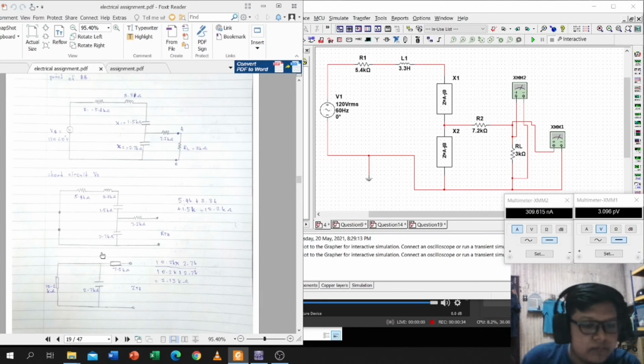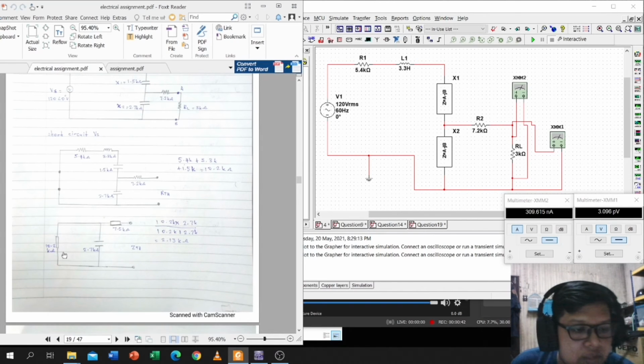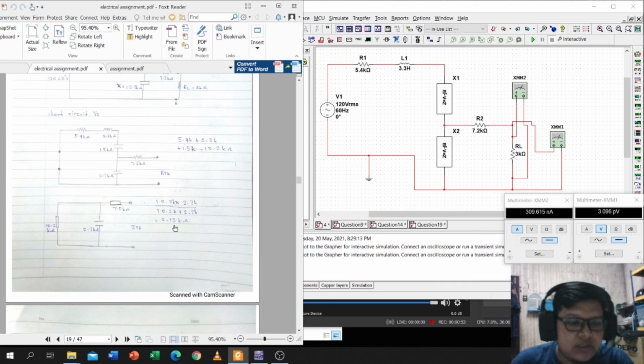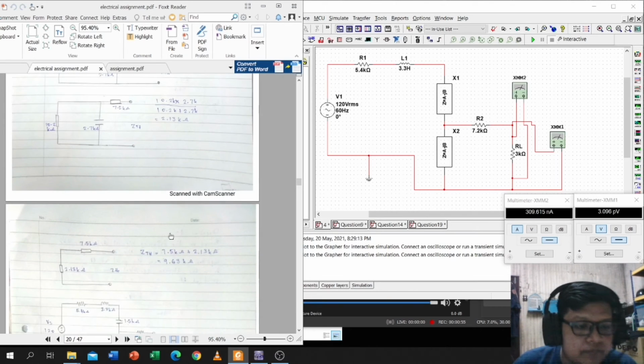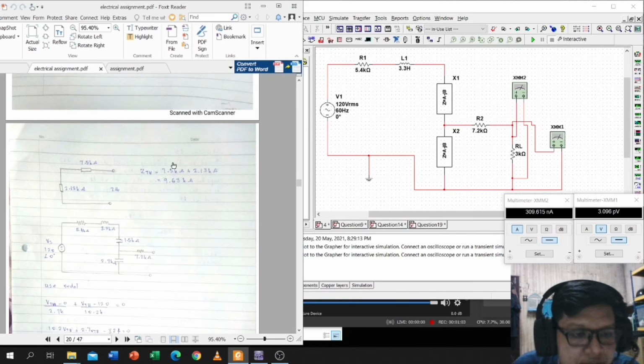and then add the resistor here. We got 10.2, and this one goes parallel with 2.7 kilo ohm, and we got 2.13 kilo ohm here. And then the way to get the ZTH is just add the resistor here, and we get the ZTH.